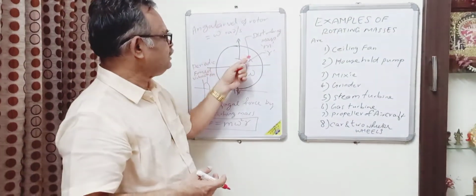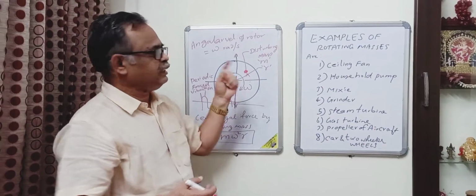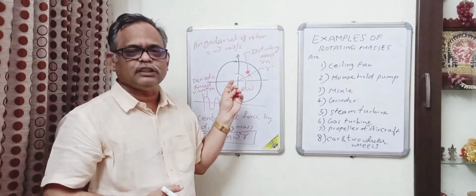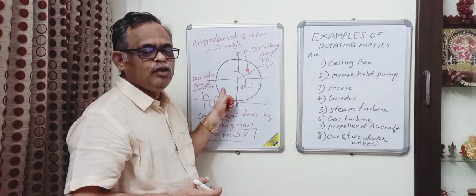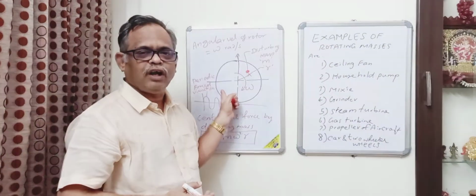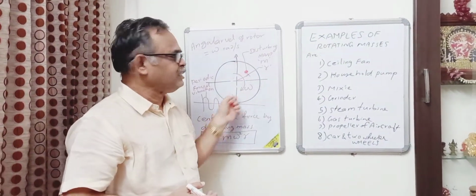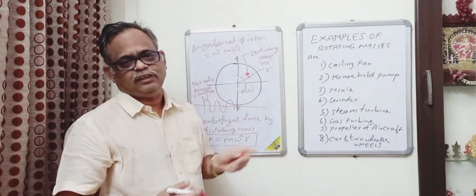And to balance it, what do we do? Just opposite it, exactly opposite, as I explained in the other case, right? Just previously, by adding a balancing mass at a particular radius R1, we can balance it, right? And the vibrations can be minimized or arrested, right?